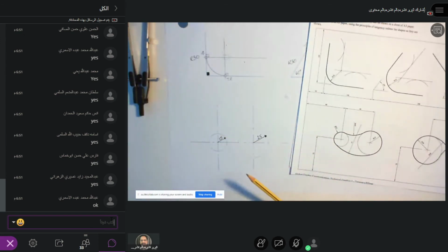So how does that help me? Well, I've got a fixed point here and a fixed point here. If I deal with this little belt at the top first, that's got a radius of 40. Now the curve comes round and just touches this circle here with a radius of 40. That means the centre of the bigger circle going round there must be 40 millimeters away from here, 40 millimeters up here somewhere.